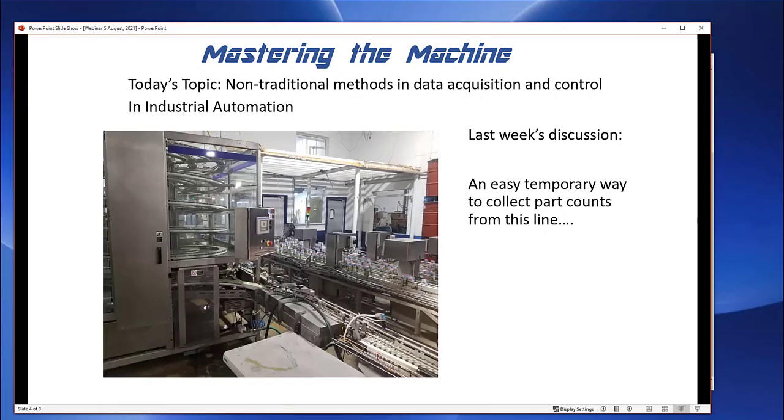So I did see a big motor, and you were gathering a bunch of data from that, vibration data and things like that. And we talked, and Phil's method of analyzing those, I guess they use fast Fourier transforms and things like that to analyze waveforms at a much, much higher rate than PLCs can do.